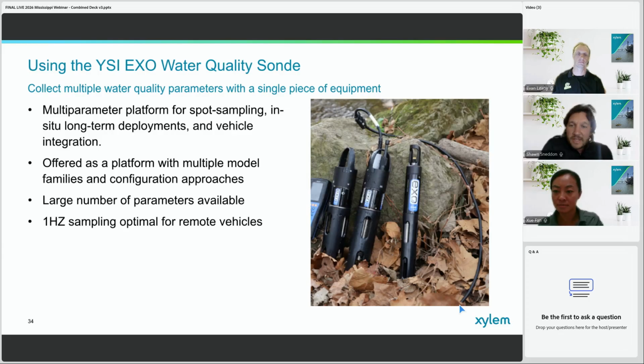So the EXO guard that you're actually seeing in the picture right now helps with any interference and optimizes the sensors, like turbidity and chlorophyll, at the point where they need to measure. So yeah, when it is installed in the EXO whale attachment, it is shaded. It's not going to have any interference, and the way that it's built helps break up the disturbance so that there's not an influence of bubbles that gets trapped over the sensor face. So yes, I think that should cover that.